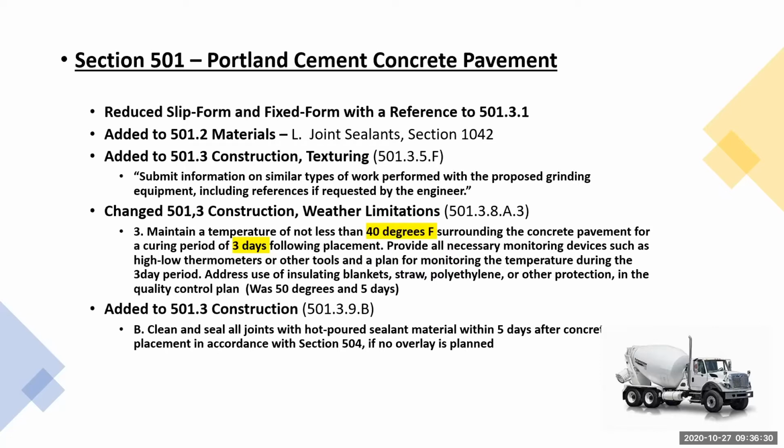And there were some differences between the 700 curb and sidewalk expectations and 501 expectations. Again, they're cross-referenced back. If you're doing concrete, you're doing concrete, whether it's roadway, sidewalk, or curb. Concrete is concrete. It has the same properties. It needs to cure out in the same time frames, because we are looking for different strengths depending on the application and performance. So they do all go back to the same cross-reference. Just something to really pay attention to.